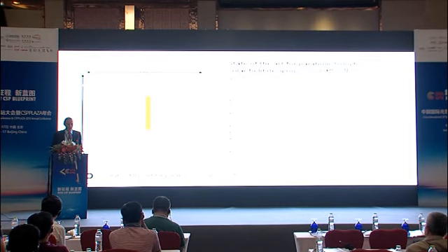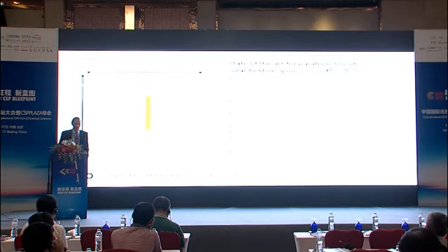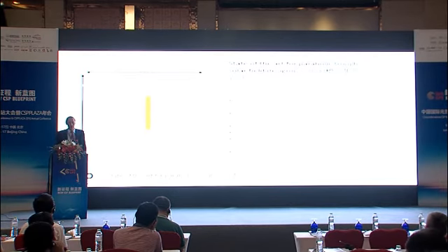Generally the designs coming from Spain with an RP3 collector structure are done with a row distance of 17 meters. The solar field is oriented north to south, and the collector is sitting on level ground. That means we require sites which are very level, and if they're not level, we spend an enormous amount of money to get them leveled.